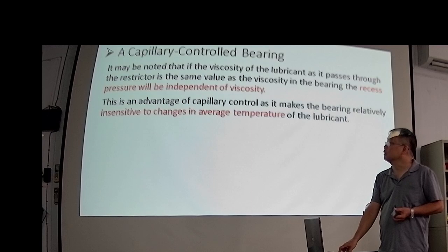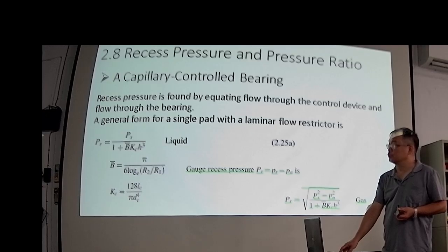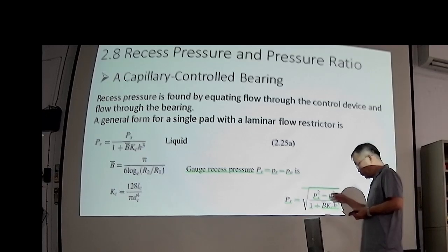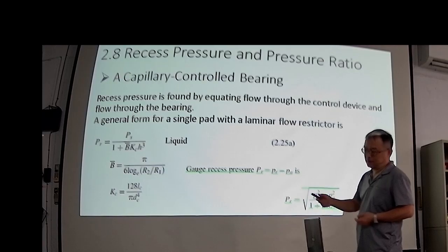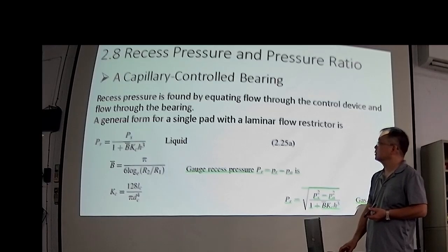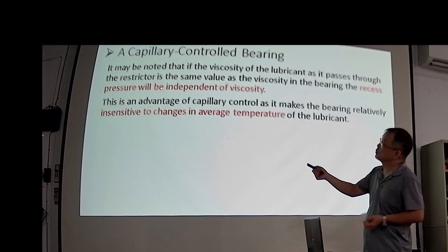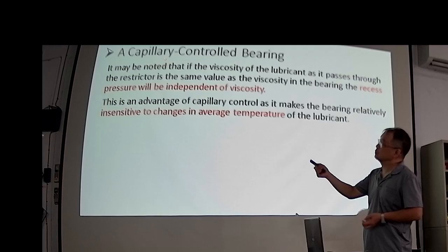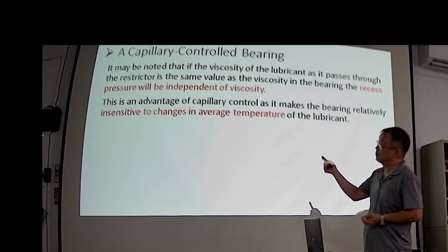And last time we also told you the conclusion. For the capillary restrictor, the PR is not related to the viscosity. So the recess pressure of the capillary controlled hydrostatic bearing is independent of viscosity.